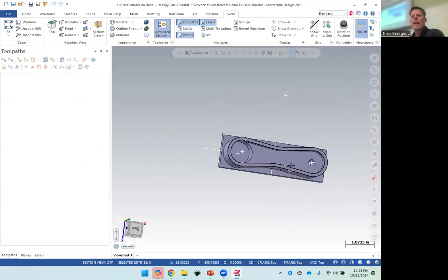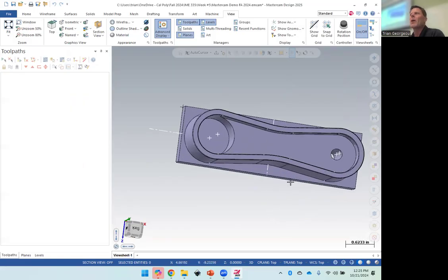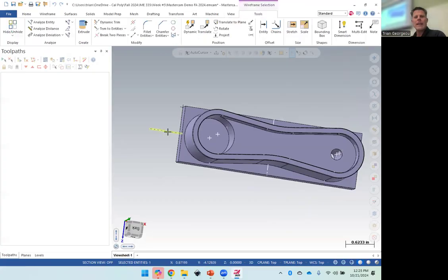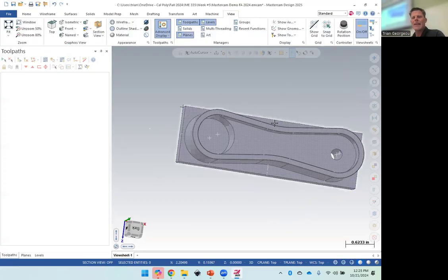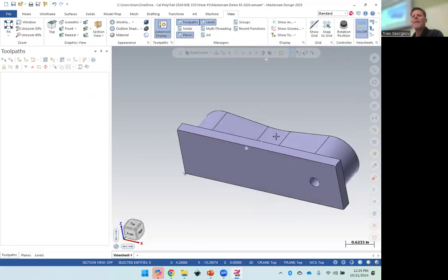And for some reason, I had these center lines because I just made a part and mirrored some stuff this morning. It saved this center line and that center line out of my model. I've never seen it import center lines before, but go ahead. I'm going to press Control Z to show you that. And that's your friend. Control Z undoes something, right? Command Z on the Mac. So we'll click on that, and we'll click right there. Also, I don't need these center points for right now. I'm just going to click on them to delete them. It puts center marks for the circles. So I have my model in here.